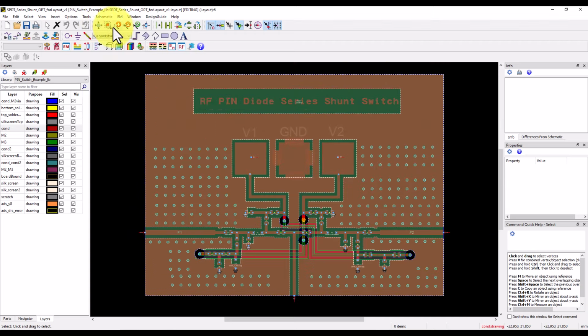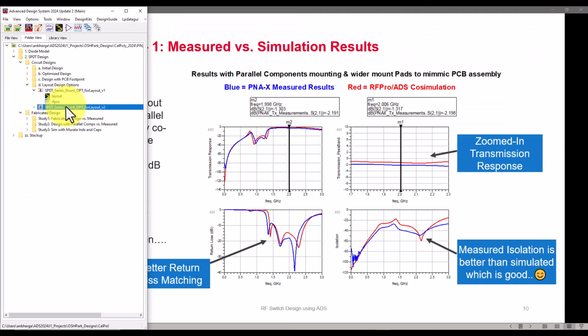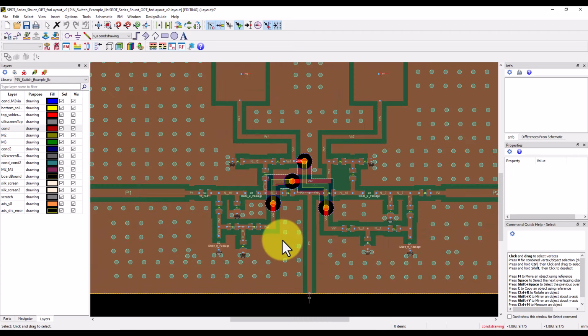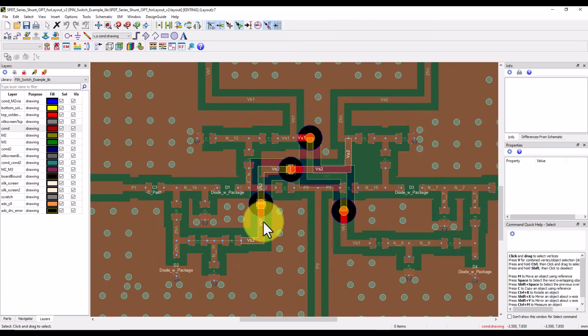So this could have X performance, and suddenly if you give it to somebody else, which is another layout engineer, he might end up doing a layout like this, where your crossover is minimal and also the interconnect is much shorter compared to the earlier case, because he simply put enough thought to rotate this section here so that you can minimize the length of this interconnect or the via transition which is happening here.